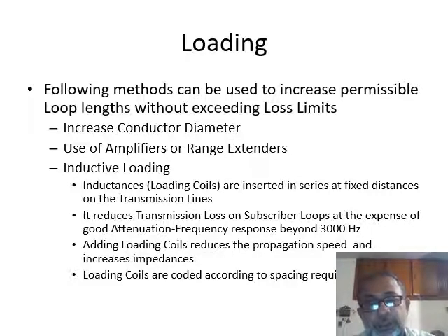So this would reduce the overall impedance of the link, and would definitely increase the distance up to which a signal can go easily. So we need to have some coils. These are also called loading coils, which are basically inductors.